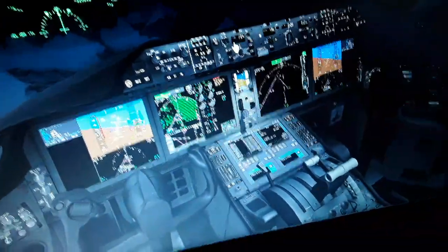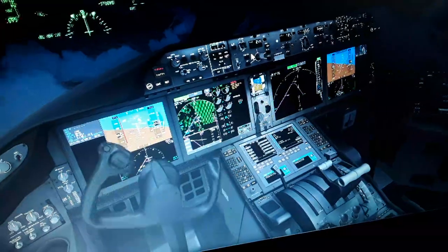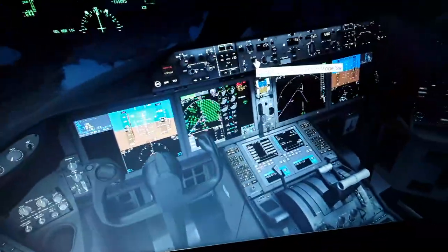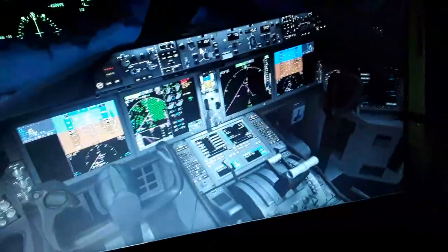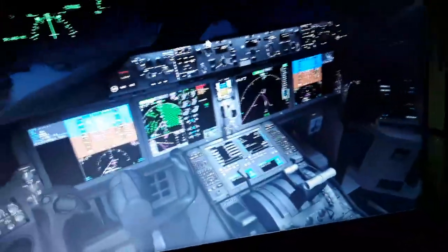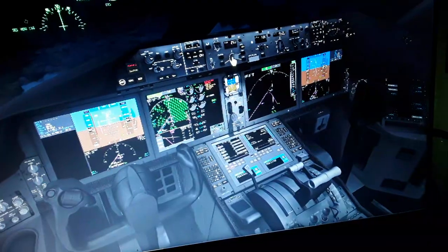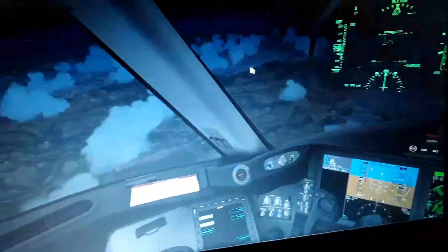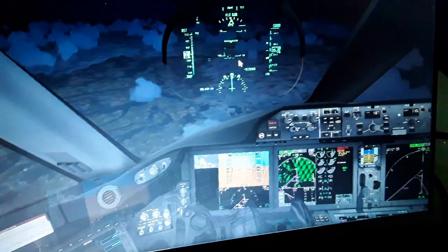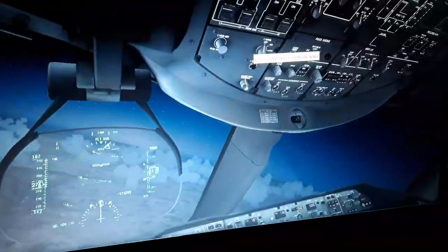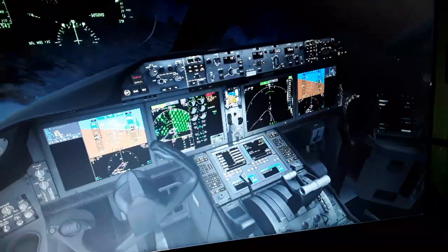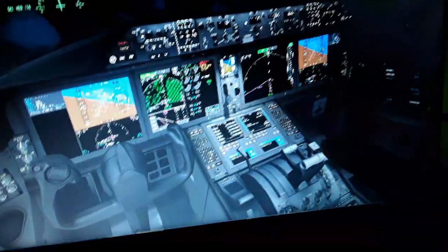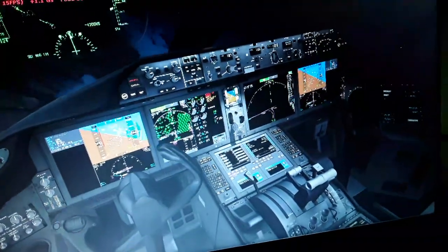So extend landing gear. The autopilot disconnect, and we take manual thrust again, and we keep descending, and we're gonna have this airspeed. Gonna make a more steep approach for the landing. As you can see, we can do that and extend some flaps. Start extending them.